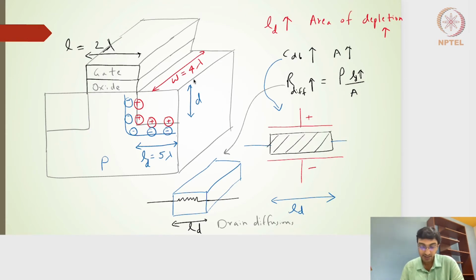Now this is again a cross-section, a little bit tilted, so we have a kind of three-dimensional view of the transistor, and again it is an NMOS transistor. This is the depletion region that has been formed after applying the voltages. Maybe the drain to body voltage is 0, but still there will be depletion capacitances, as denoted by the positive immobile ions and the negative immobile ions here.